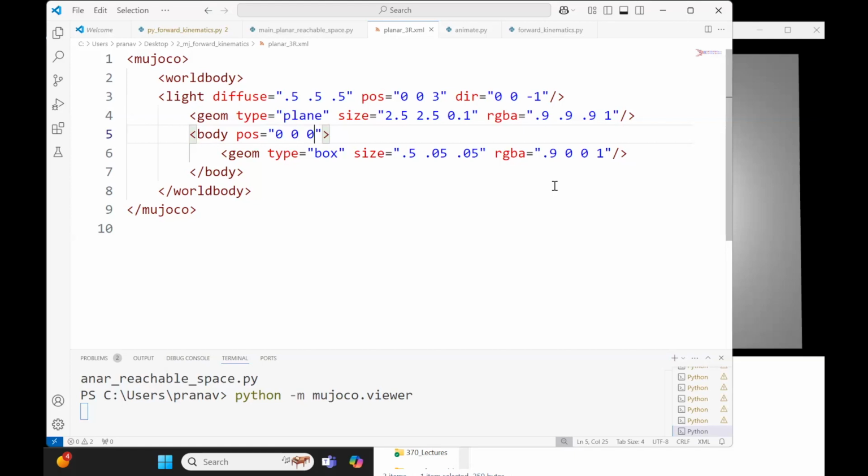Okay, that won't change much. Okay, we've defined that. Now, the starting point of any of your XML creation is to figure out where the axes are. The axis defines the origin of the frame. You always want to put the origin of the frame because once you define the origin of the frame, the axis, you can use that to then set the pin joint and so on.